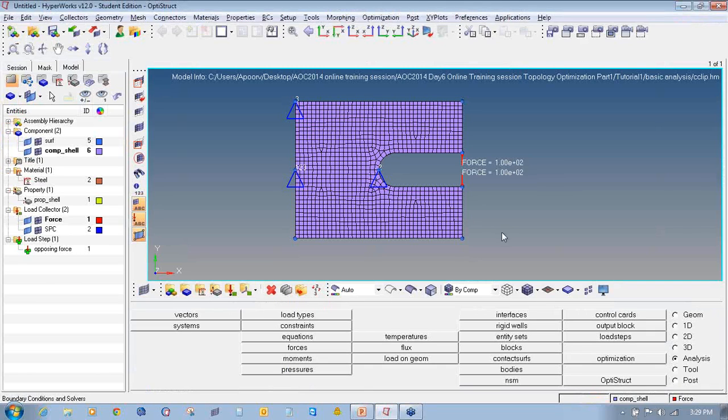So this is my minimum required displacement. I should not go below that. Somewhere near it's okay. The forces in the structure are applied at the outer nodes of the opening of the C-clip, making those two nodes critical locations in the mesh where the minimum displacement is likely to occur. So in this tutorial, we will apply a displacement constraint on nodes so that they would not displace more than 0.07 in the y-axis, either positive or negative.